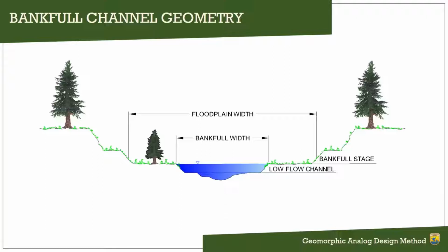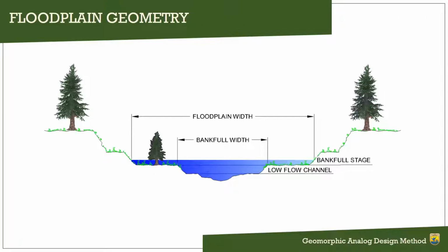The bankfull channel dimensions are also the primary drivers of sediment transport in a natural stream channel. The reason for that is once a channel spills onto the floodplain, roughness increases and velocities decrease. So out in here, we're getting higher roughness and lower velocities, and the larger sediments drop out, as Matt explained in his presentation yesterday.